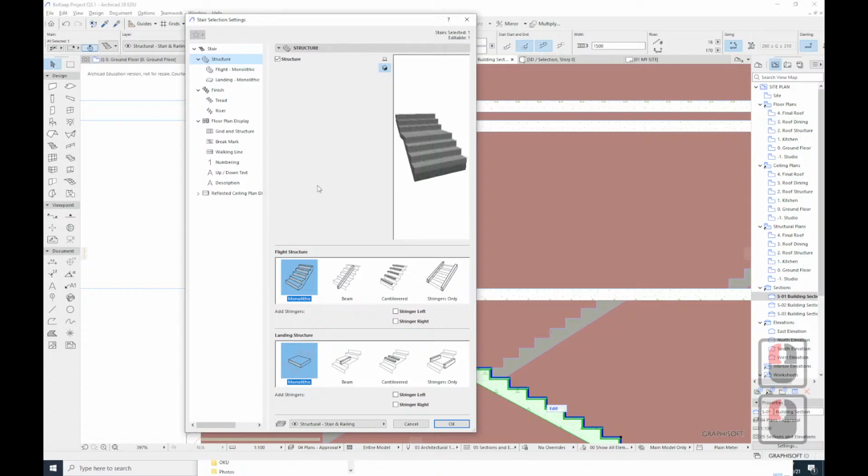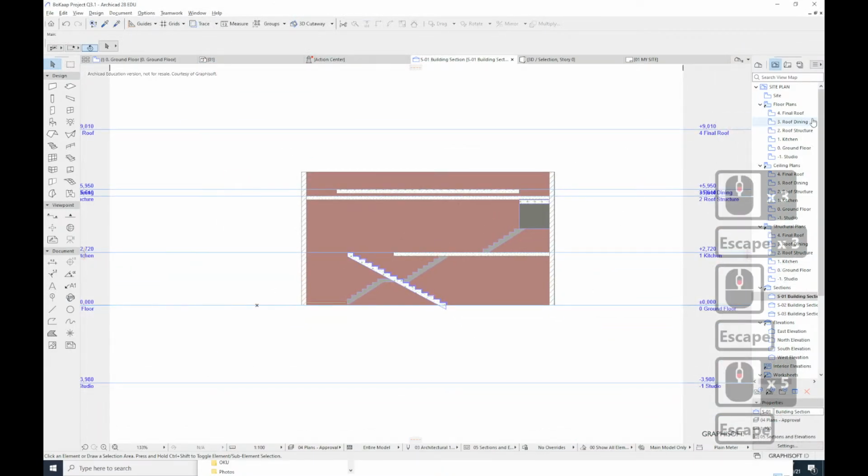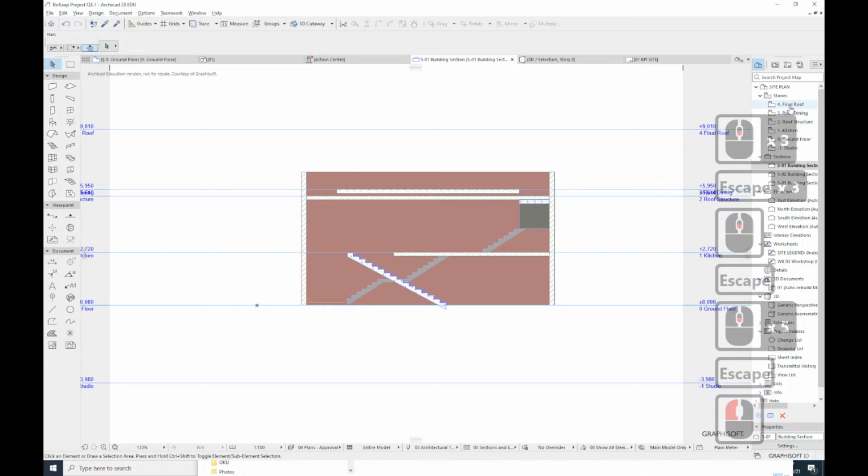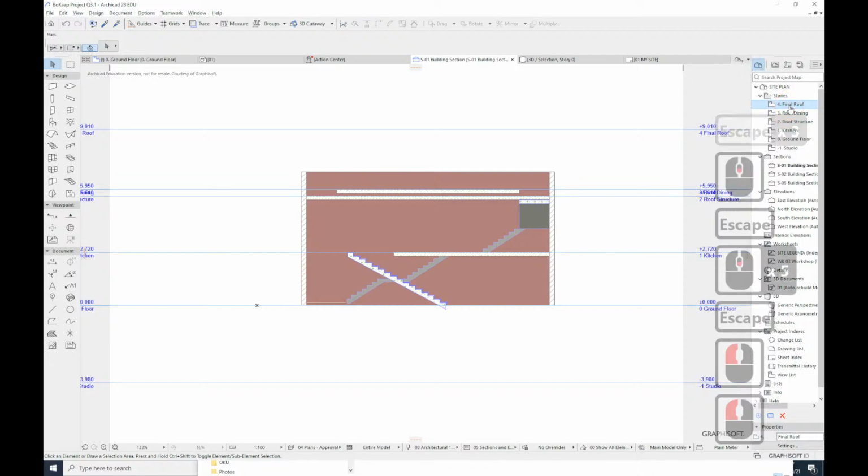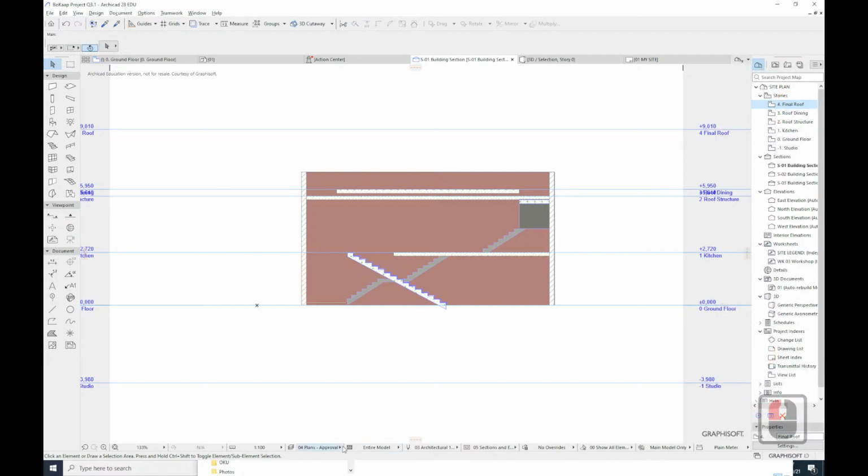Okay. I don't really know what happened all of a sudden, but I can explain something. This view sometimes shows things in a very strange way. I want to show this as... So just pick the correct layer combination. Here you want to show entire model. Here you might just be seeing finishes. So just check this, okay? You see this entire model. So now this is better.